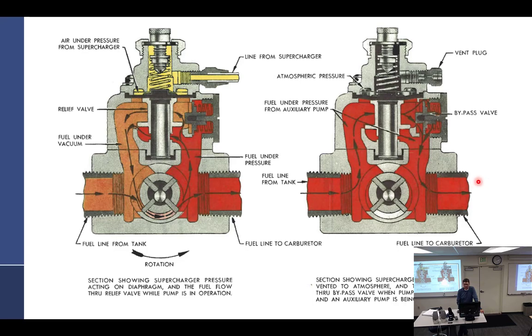All right, once the engine starts and this starts spinning, when will this close, by the way? That's going to be my question. What pressure, or when does that bypass close? When the pressure is greater at the pump. Which pump? The main pump. When the vane pump exceeds the boost pump.